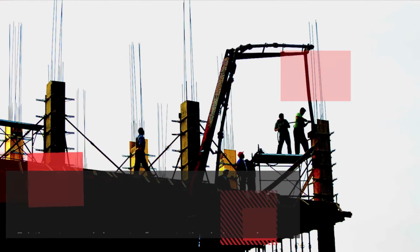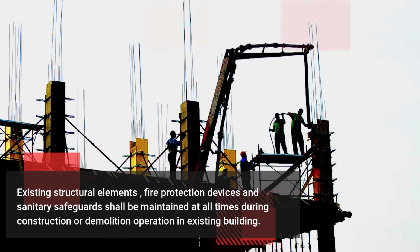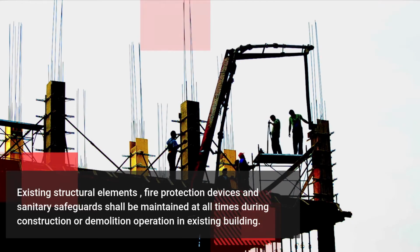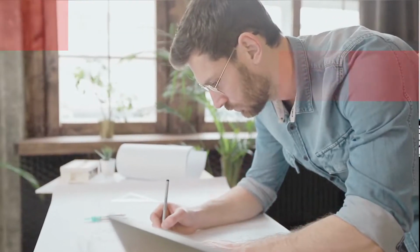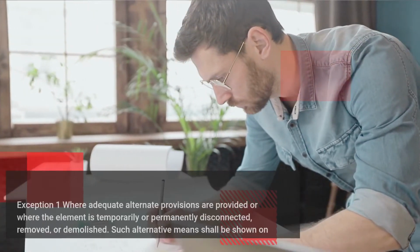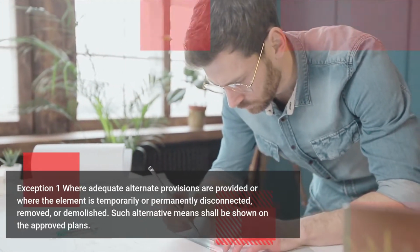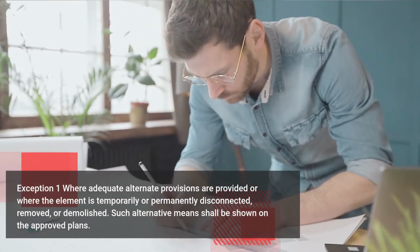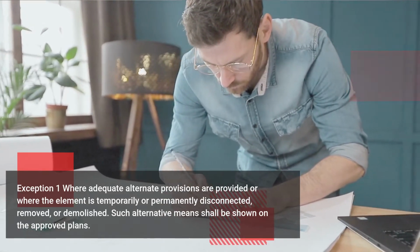Existing structural elements, fire protection devices and sanitary safeguards shall be maintained at all times during construction or demolition operation in existing building. Exception 1: where adequate alternate provisions are provided or where the element is temporarily or permanently disconnected, removed, or demolished. Such alternative means shall be shown on the approved plans.